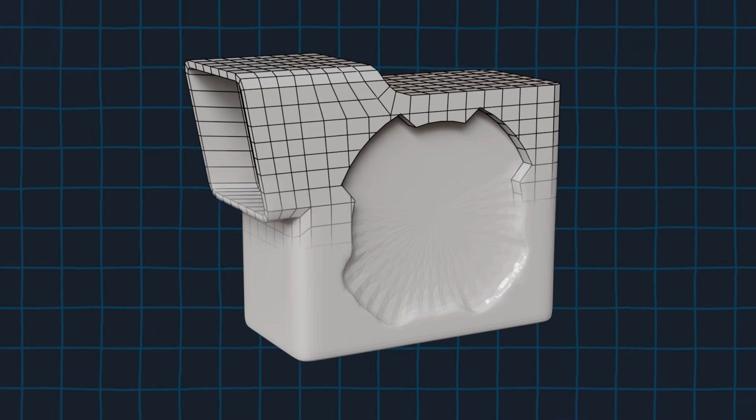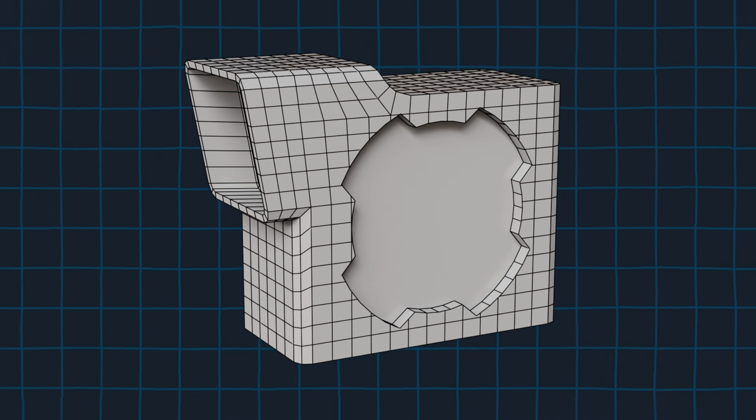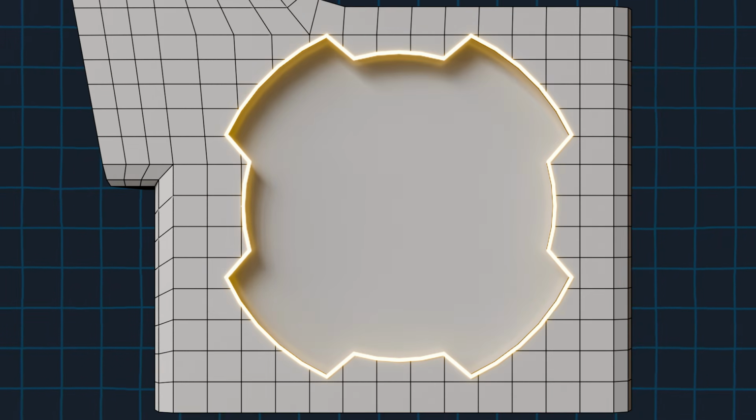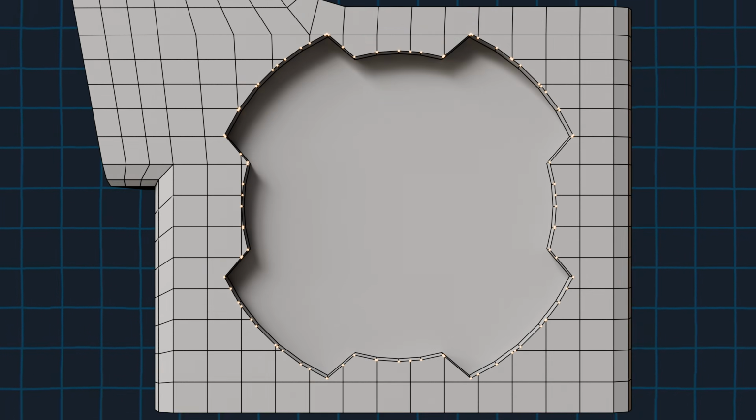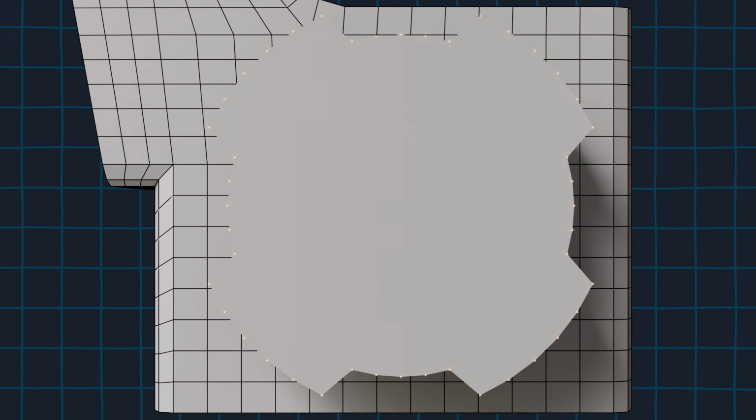We will remove the subdivision modifier and work on converting the mesh to be quad-based. We will turn our focus to this edge, specifically the vertices on it. I don't know if you noticed, but we have a lot more vertices on this edge than we did on the Boolean object. The Boolean object has 44 vertices and our mesh has 92.